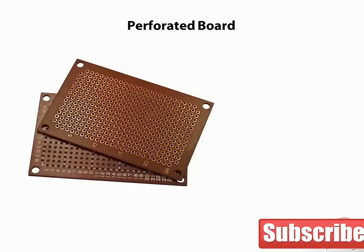Perf boards are a step up from breadboards. They allow us to insert components through holes, usually spaced 0.1 inches apart. The leads can then be bent over on the other side and connections made by soldering leads and jumpers together. Some perf boards have copper traces on them that you can use as a pseudo-printed circuit board.